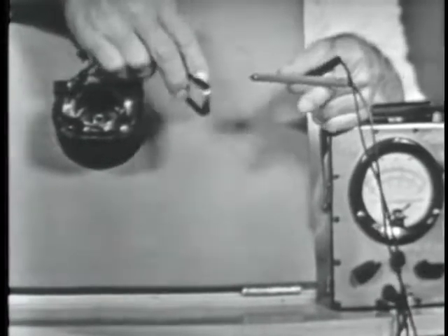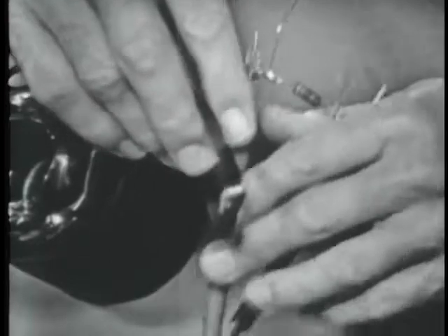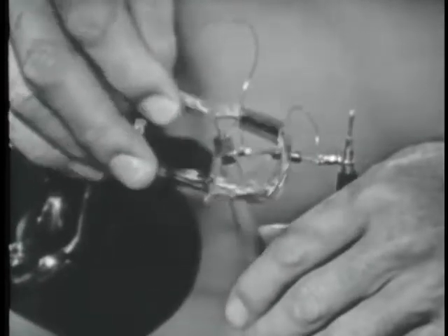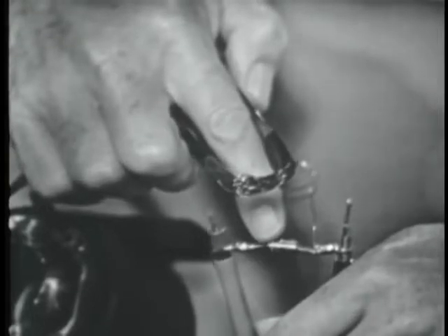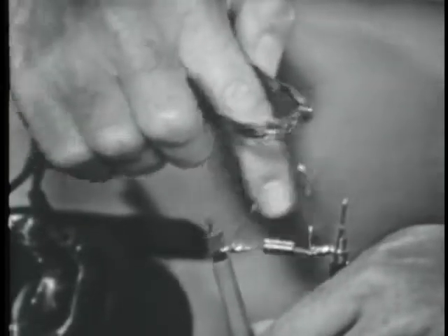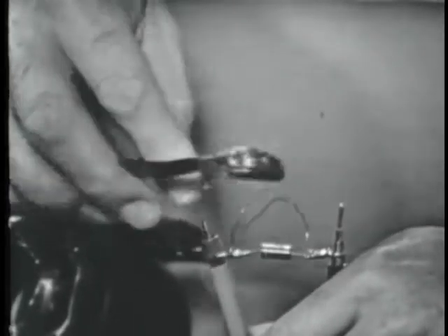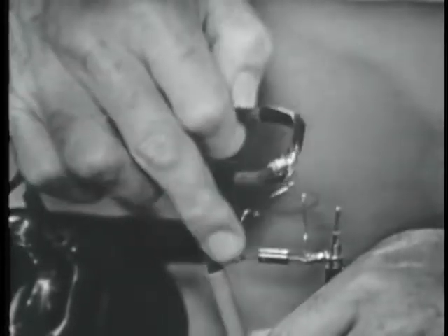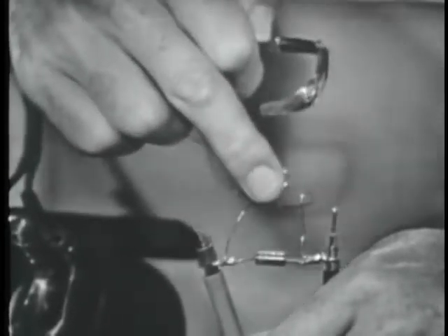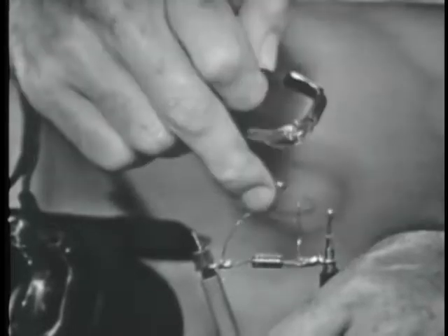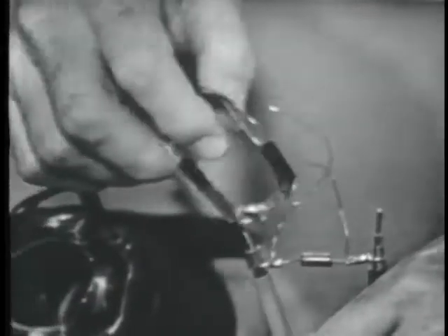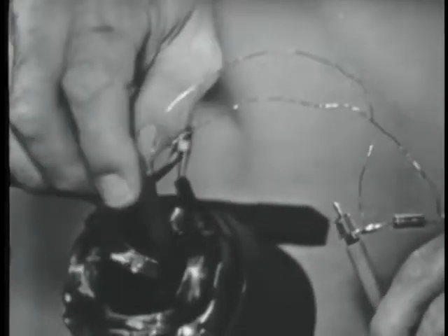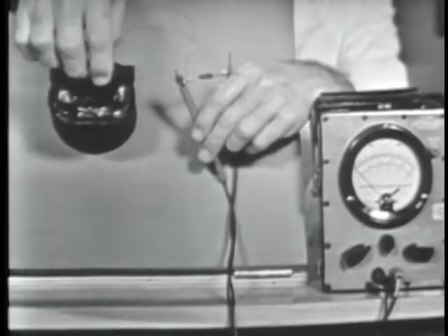Now, why don't you explain? All right, I'm going to do that. This is a coil of wire. The ends of the wire are connected to a resistor that is connected to the leads on our PSM6. And the object is, if we get current to flow in this loop, we'll have current flowing through this resistor, we'll get a voltage drop, and we'll read the voltage on the PSM6, okay? All right, now I'm going to take the loop of wire and place it in the field windings.